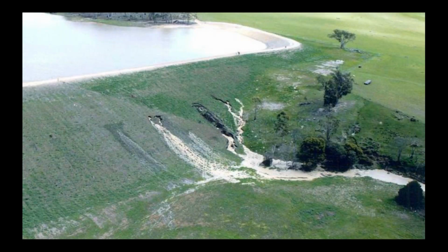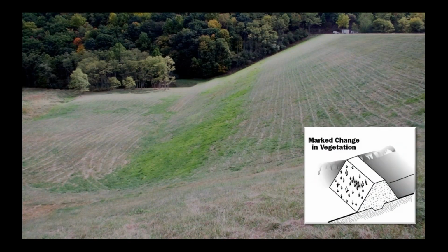So just going back to uncontrolled seepage, the big solution there is to have a chimney drain and a filter diaphragm, especially around the conduit. If you have that feature, I'm not aware of any dam that has ever failed because of uncontrolled seepage that had that modern defensive measure. If you have a chimney drain with a blanket drain and a filter diaphragm around the conduit, chances are you will never have to worry about that.